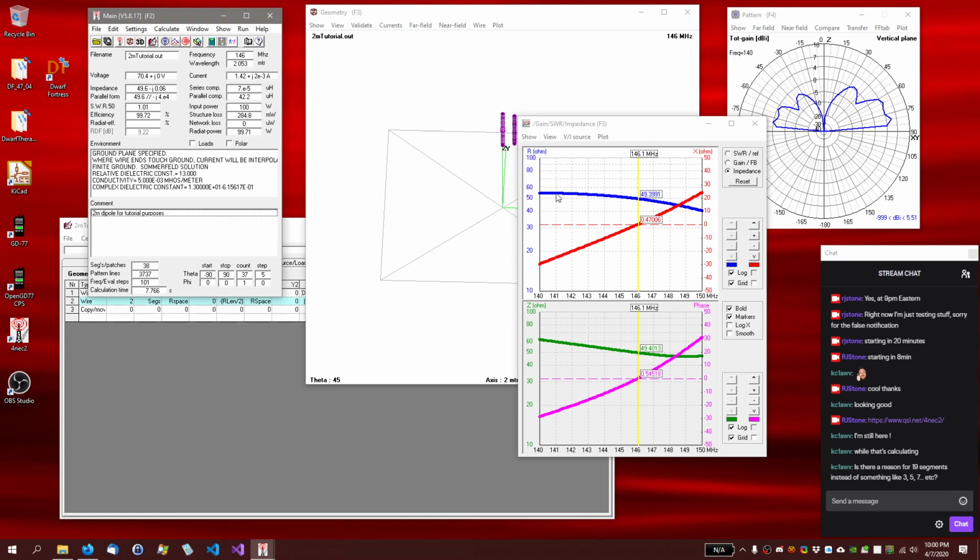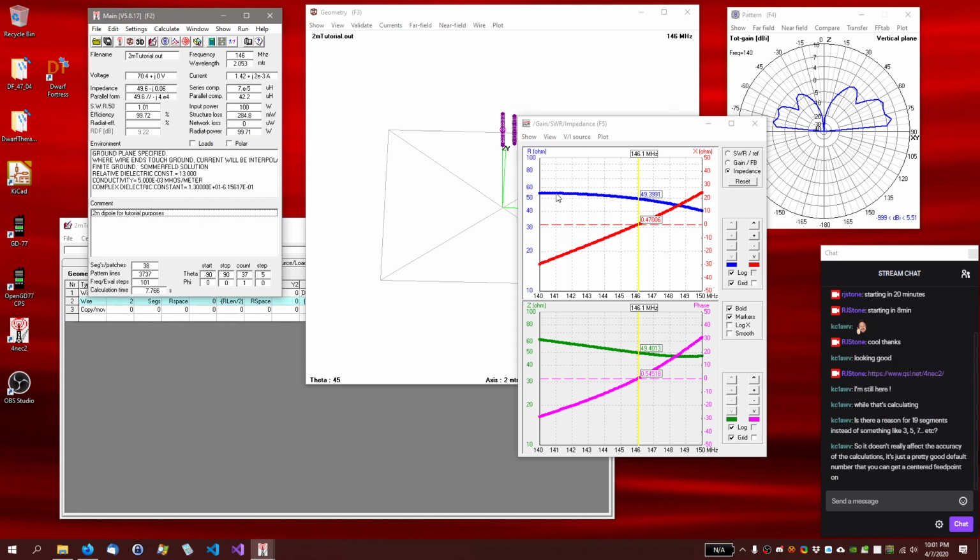There is a problem with segments that are too short, if the ratio of the radius of the wire to the segment length is too small, like if the segment is only as long as its own diameter or something, you end up with a squat cylinder.